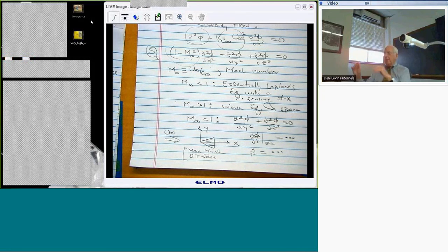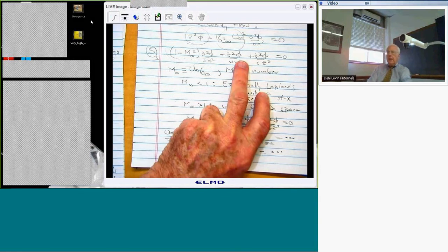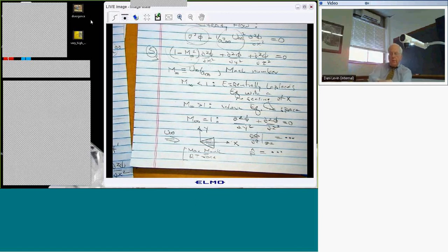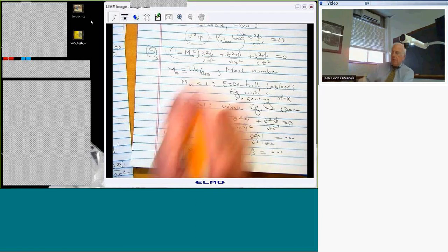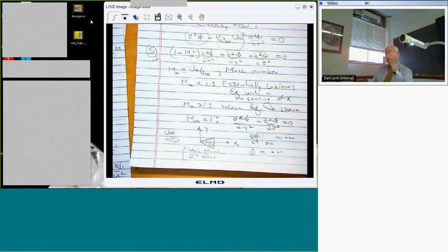But it's not because this isn't okay per se. It's because I left out viscosity. It's not a failure of the potential flow theory as such. But it was only when people actually built low aspect ratio wings, where the flow separation is much less of an issue, and they went to the wind tunnel and made measurements and compared it to this slender body theory, they said, oh, that's pretty good.